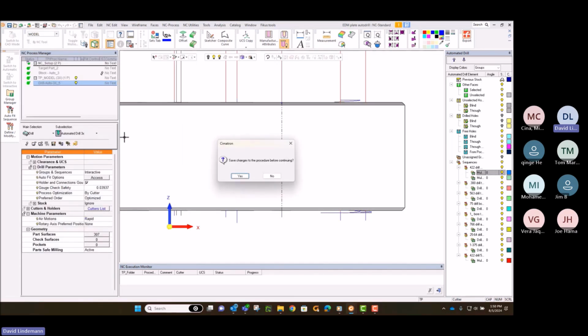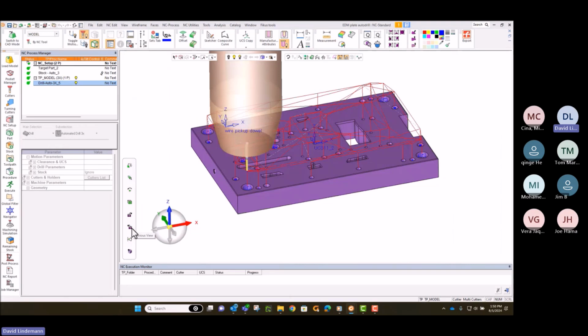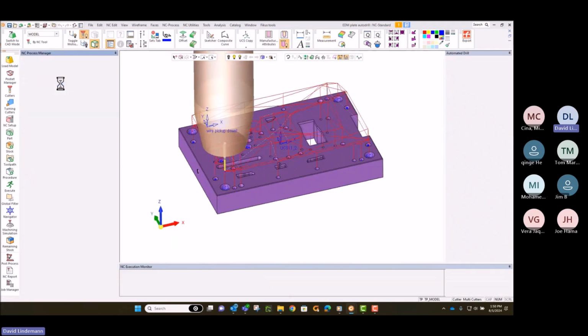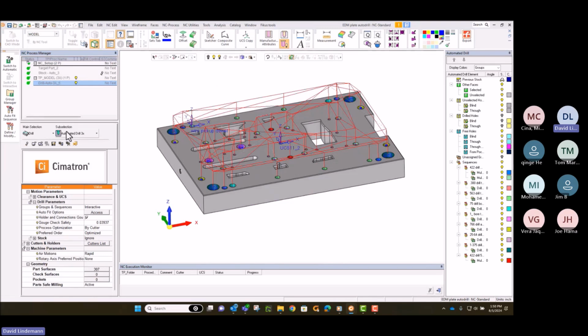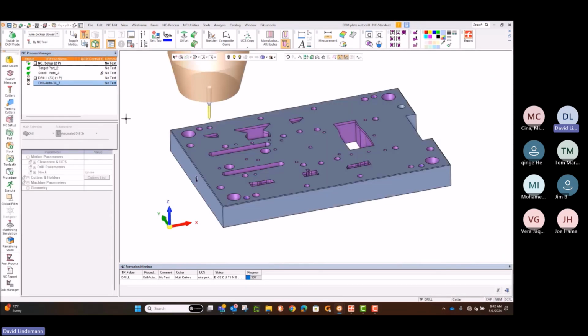So typically, a lot of stuff would be drilling, high-speed peck, counterboring, drilling, tapping, over and over again in this one step. It will find all the holes for me and go out and grab them. Plus, there's some smarts to it. We'll go into calculating it, and then we'll do a simulation of this. So maybe it's used the same drill three or four times with different holes, or something like a spot drill. Especially, it would use that.